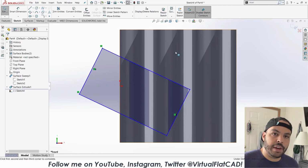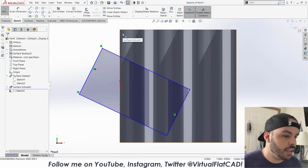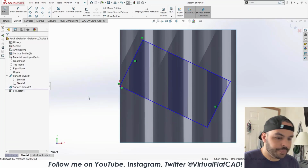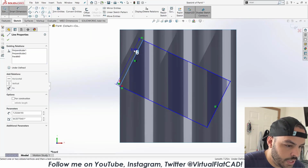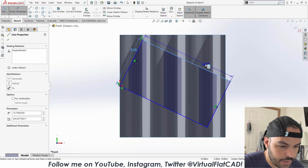In case I have to redo the surface in some other way, if this corner is attached to that surface, it's going to say, hey, I can't find my buddy anymore. Where'd he go? I don't know where to be. Whereas the origin is very persistent. It's the most persistent thing. It'll never lose that location. So now I can make a size, so maybe I'll make that 8 inches,